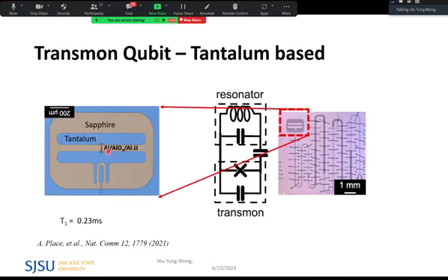And I said earlier, I don't need to form the gate because I'm going to put the qubit here, and then I have a transmission line going all the way to a port. Then how do I operate on this qubit? I apply a gate pulse. Then the state of this Josephson junction, which is a linear combination of 0 and 1 extra Cooper pair, will change. The alpha and beta will change. And that is how we operate a qubit. Okay.